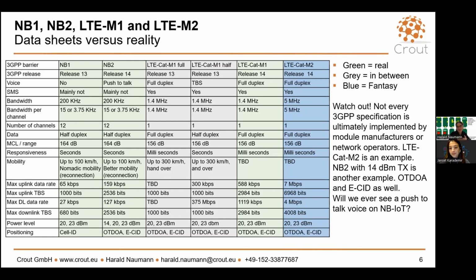The more data you transmit, the more you have to pay, and the higher the energy consumption. But the other way around, 50 bytes to 250 bytes are the common values for both worlds, for narrowband IoT and LTE-M. Yes, you can do more, but then we are moving far away, more towards LTE Cat 1. So the question is, what is the application? Nobody will stop you from transmitting more. The only one who will be happy is the operator, because they make more money with the application.